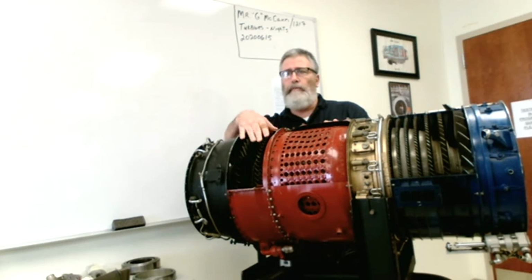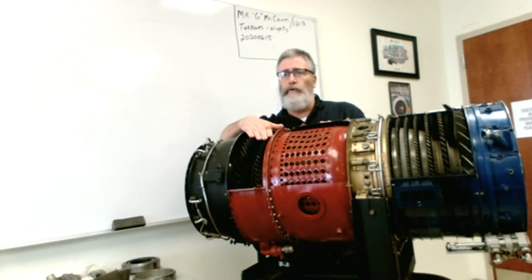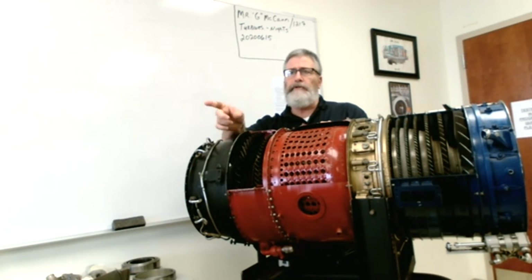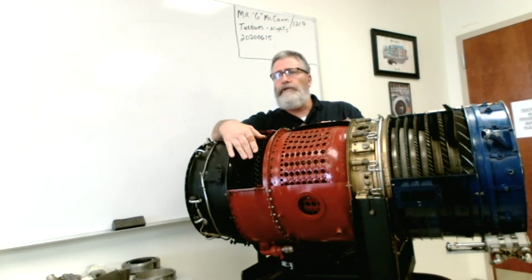All right. This is a very important component. If the dump valve is stuck closed, then when we shut this engine down, we will have a pool of fuel in there. So one characteristic is that I shut the engine down and I notice that the temperature rating is going up instead of down. That means that this fuel inside here is burning. The procedure there, it's not a dangerous situation.